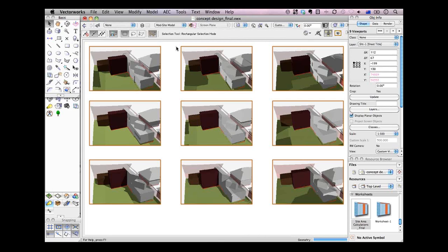When you create a site model, I haven't got time to go into all the details, but one of the options you've got in site modeling is to create a boundary for your site model. So you can create a much broader site model and then cut it down so it just looks like it's your site, but actually the mathematical information goes out in both directions. It was actually much bigger. My original site model was huge. It was like 3 or 4 sites wide.